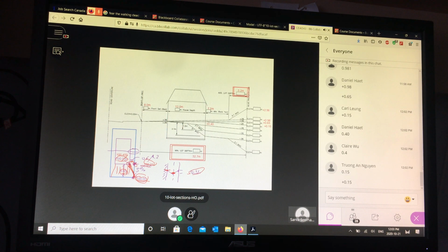Okay, so this is just an intermediate step, 0.4. So you come up 2% and then down 2%. So the final thing at the back is all we're interested in, positive. So if the backyard and the front yard are compatible, they're almost the same. The backyard's a little bit higher, but not much. You would have a split point right there. So the side between the houses would drain to the front, and the front yard always drains to the front. But the entire backyard drains the other way.